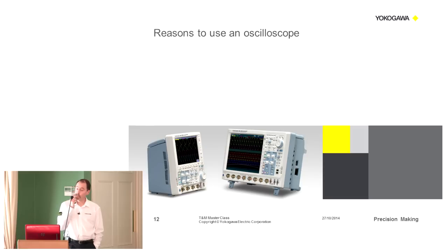So what I'm going to do is give you a few ideas. I'm going to give you a few pros and cons of the different types of instruments for measuring power. And I should say that when I talk about power, it means different things to different people. Because if you say power to an RF person, they'll be thinking of microwave power. We are basically talking about low frequency power, mainly to do with the supply frequencies as the fundamentals, 50, 60 hertz, for instance.